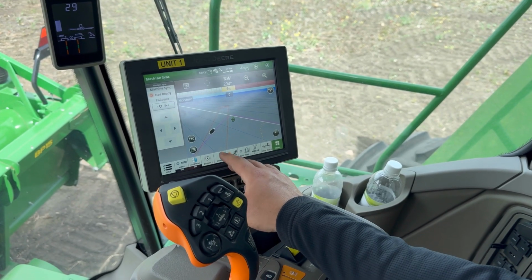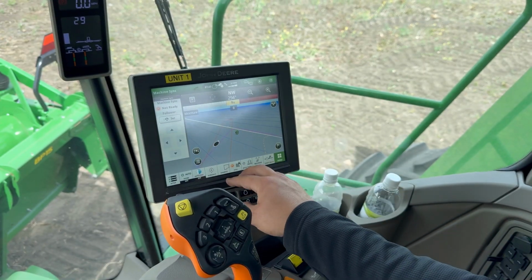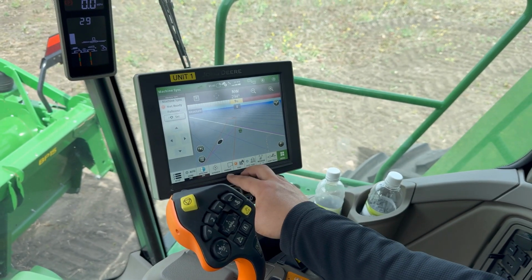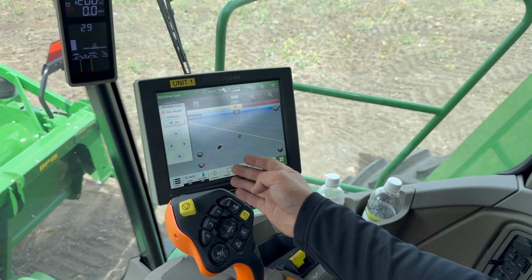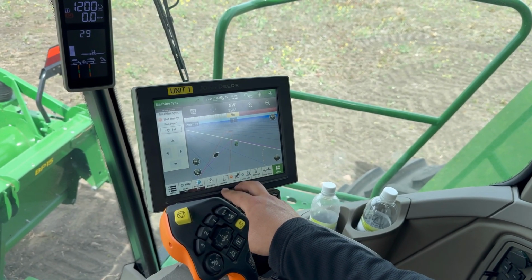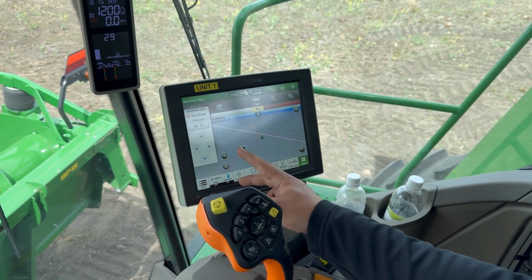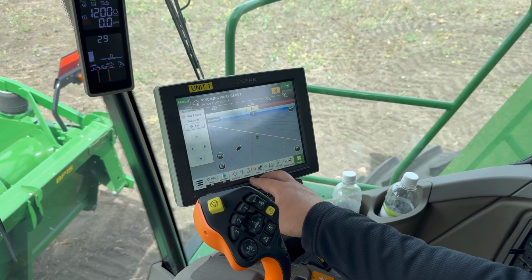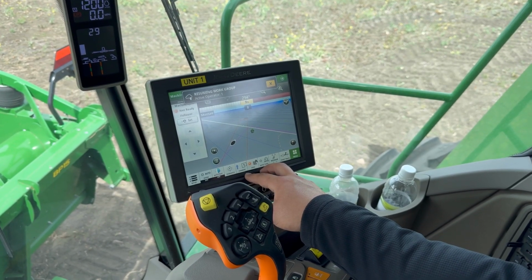We will see for our 4 levels, we'll see not ready for machine sync, meaning that right now we just don't have communication. Going forward, once the tractor enters the operational zone with the grain cart, we will see that change from green to ready. And then once auto track is engaged, we will have acquiring with a blue dot, and then it will now move to tracking with a blue dot once we have that all engaged.